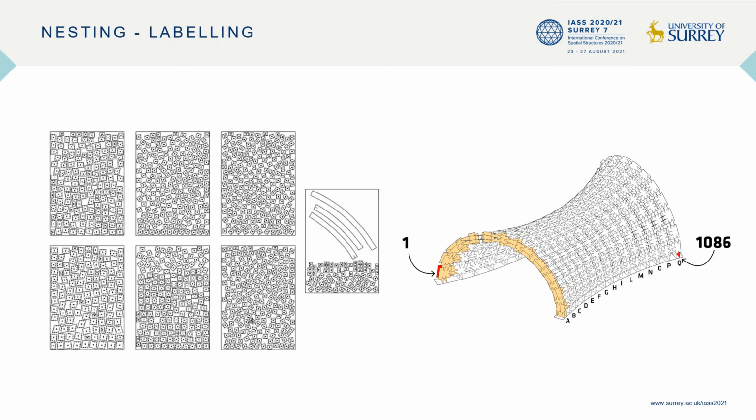The system has been further tested through a digital fabrication process. For this purpose, a temporary wooden pavilion has been designed to build a 1:10 scale model. The prototype was produced using a 3-axis laser cutting machine. The cut was preceded by a pre-production phase consisting of nesting and labeling made with OpenNest, a Grasshopper add-on capable of unrolling, packing and numbering the elements.